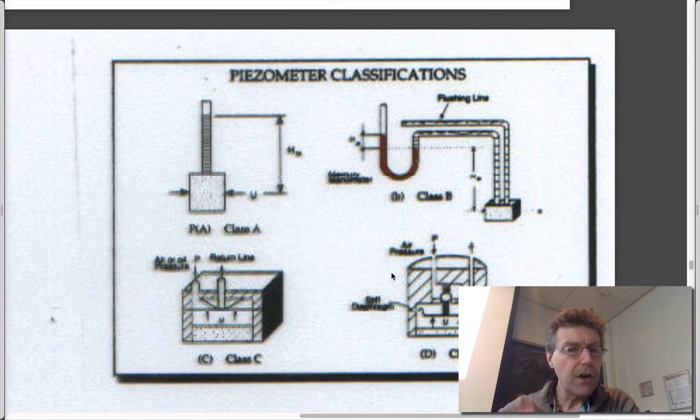And so these are a variety of different piezometers that are used. This is just a standpipe piezometer that we looked at in this previous hole. A porous zone with a pipe going out of it that allows water to flow in up to some water level here that you can measure. You can add water into it to look at the drop in water level with time and link that with permeability.